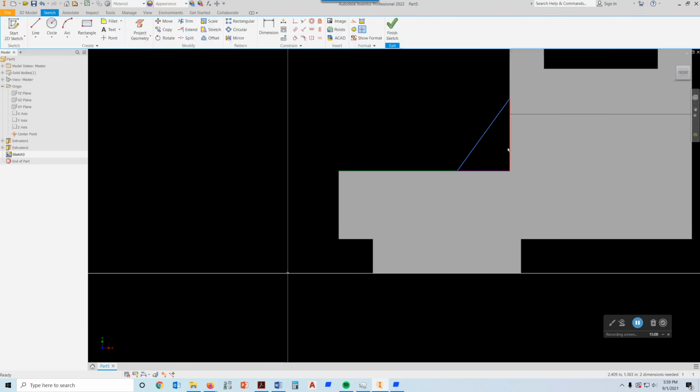Now, that sketch is just going to be a triangle, and the dimensions for that triangle, it says actually in here that it's 45 degrees. So we have to go to dimension and pick on this and pick this line right here. So I picked this line down here on the bottom and that one. I'm going to pick right there and type 45 and enter.